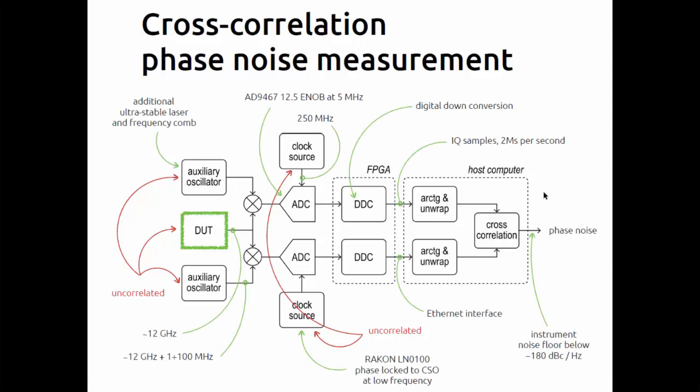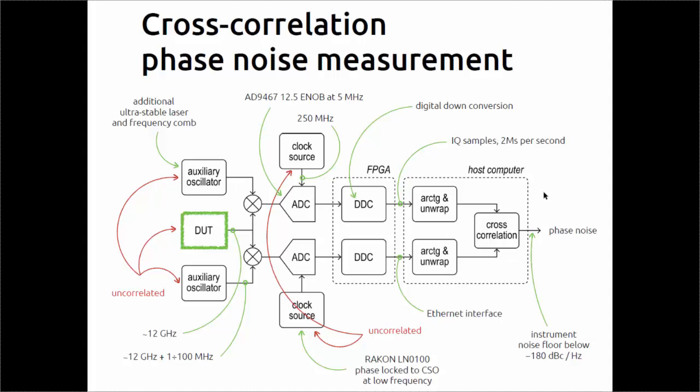In more technical detail, we implemented a system based on an FPGA equipped with very fast analog-to-digital converters from Analog Devices, with 12.5 noise-equivalent bits of sampling resolution.